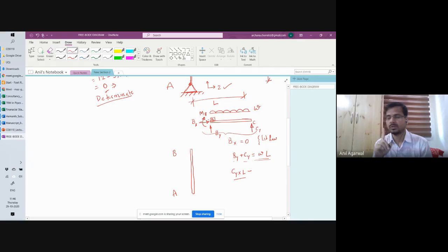If it were a bending moment, Mb would have been a sagging bending moment, right? But I will show it as a negative because it is a clockwise moment, and what I need here in this equation is a moment value, not the bending moment value. Okay, so that's where you need to differentiate between a moment versus bending moment. The way I'm using it is a moment because it's an external moment acting on this member.